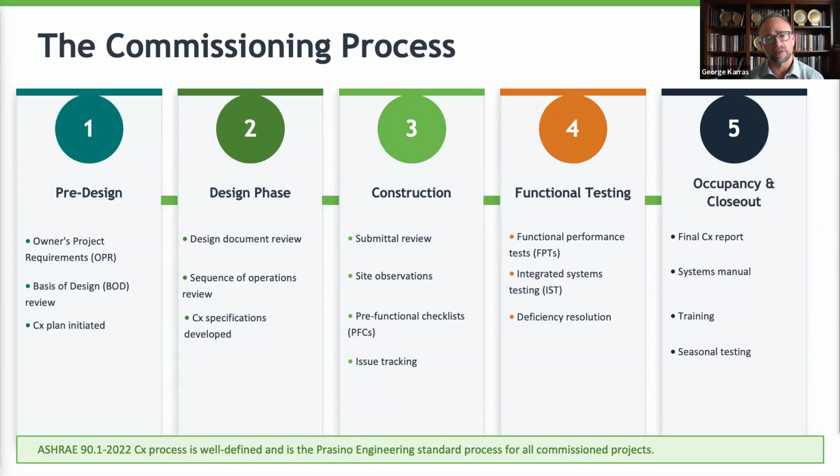Then during the design phase, you have documentation review, sequence of operation reviews, and CX specifications are developed. Within the construction phase, and this is why it's important to not just bring your commissioning agent at the very end, you want your commissioning agent also to be part of the submittal reviews, performing site observations before saying everything's done and completed and just to come on site. Also, pre-functional checks are developed, and then also issue tracking.